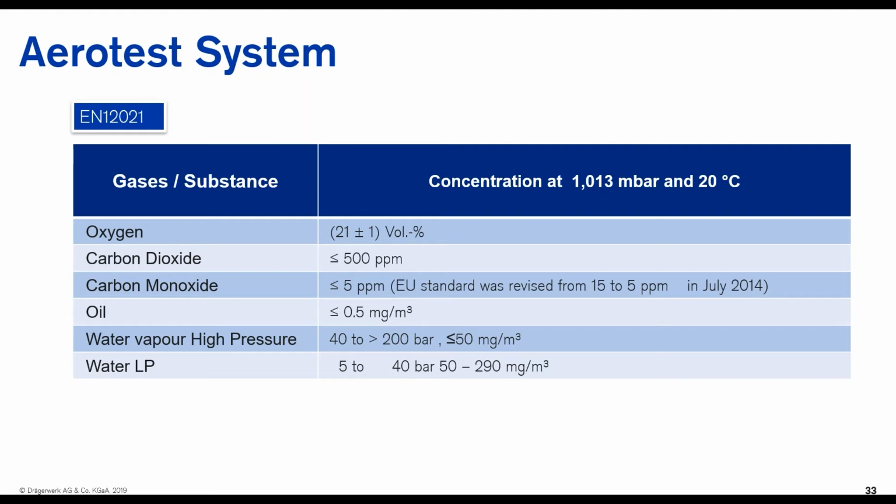Other substances, like oil: the presence of oil in the air supply will contaminate and damage the breathing apparatus. Even water vapor in breathing air is not dangerous to the wearer, but it is a concern if free water is able to form, which could result in internal corrosion or freezing of the valve that might lead to malfunction of the equipment.